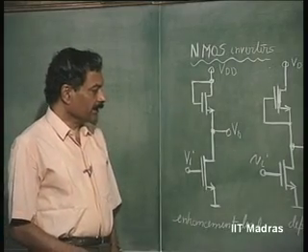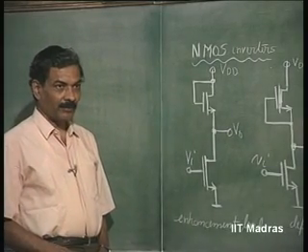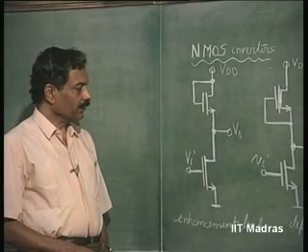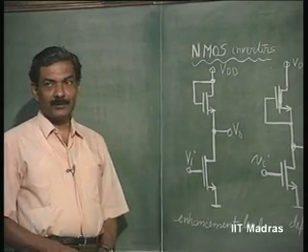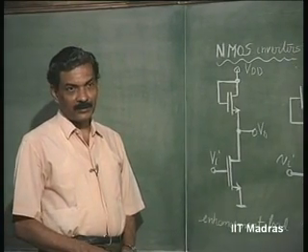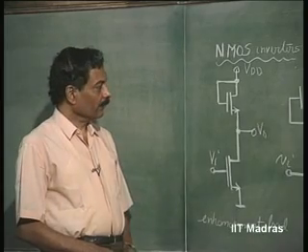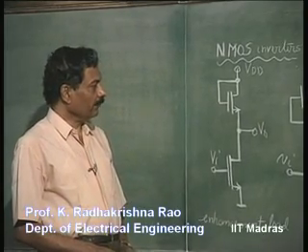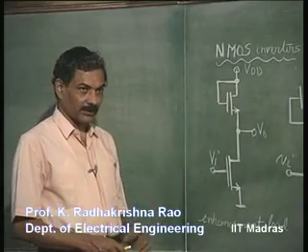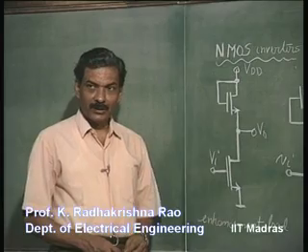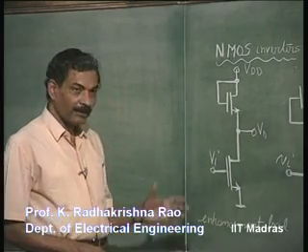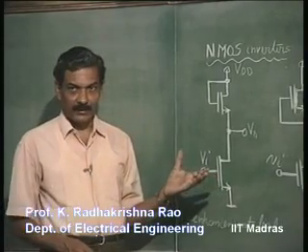Earlier we have been considering inverters or inverting amplifiers with resistive load, and then in the last class we saw how those resistors could be replaced in the case of BJTs by current sources. Now, today we concentrate to a certain extent on such MOS circuits which do not use resistors as loads at all. That is why they have become famous in VLSI design.